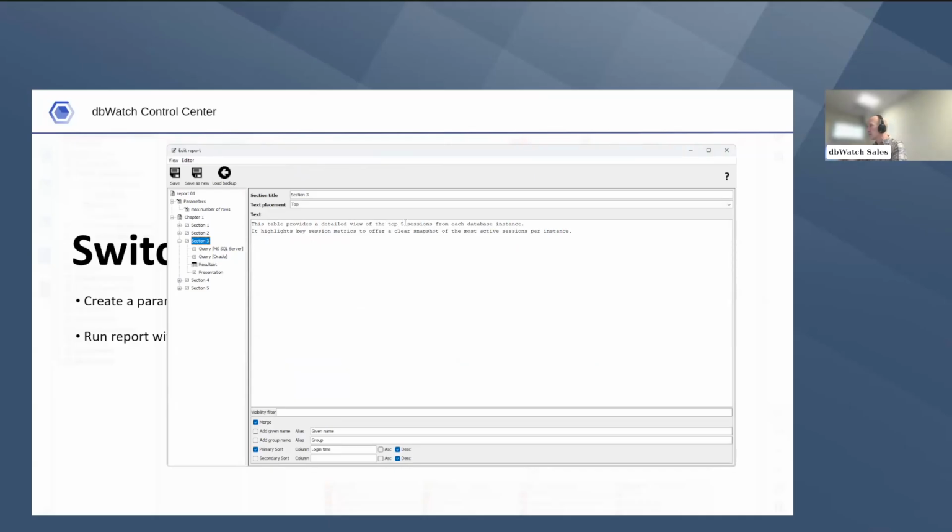So here we can also add the parameter. Unfortunately, we cannot right click, so you will have to type it manually. So what you do is double semicolons, then type the name of the parameter, and double semicolons once again. This is the way. Actually, you have to put maximum number, max, like this. So this is the name of the parameter. You have to put 2 double semicolons in front and behind the parameter name. So like this, I will click save.